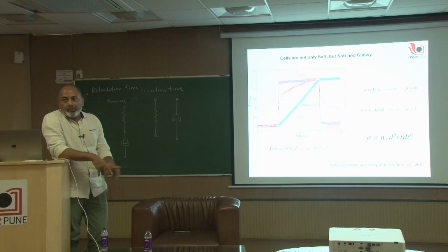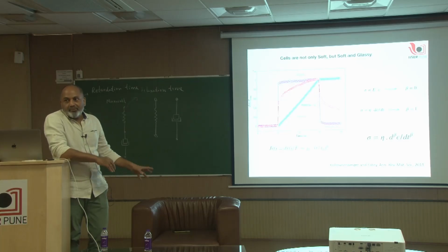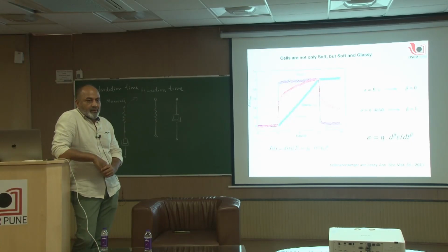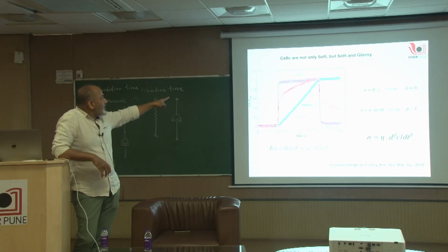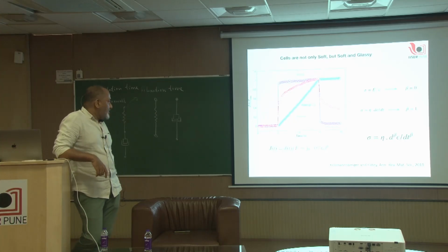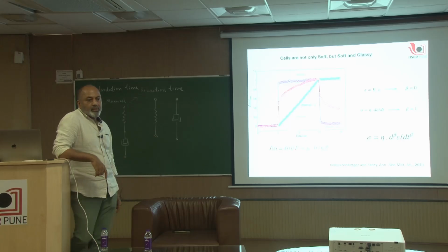Okay, thanks. We'll show you a result from our lab on how to estimate this from fitting. It's the power law exponent. If you take the stress upon strain and make a log plot, you will get beta from the slope of that. How do you get J0? Is it the instantaneous or the peak modulus? You can get J0 and the beta from these two things.